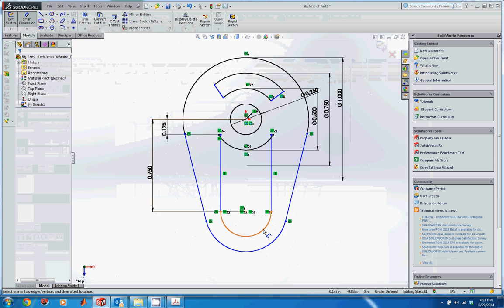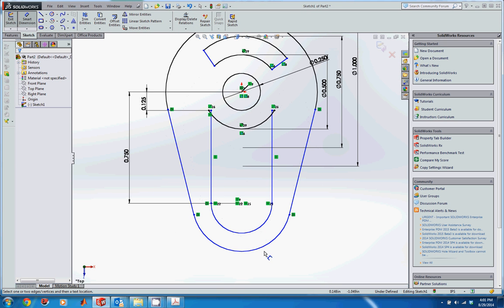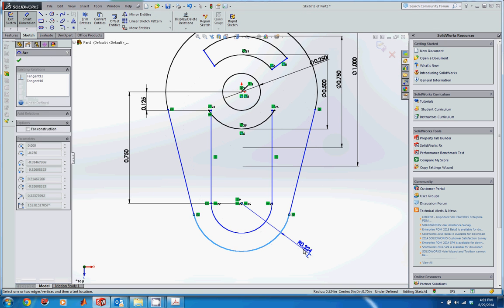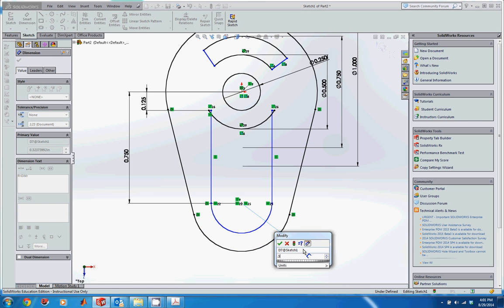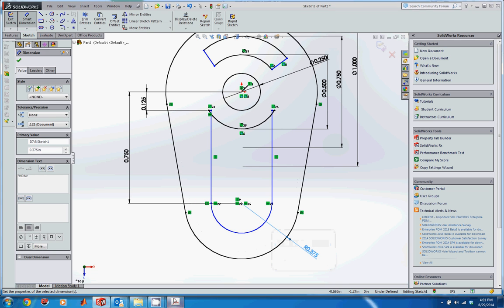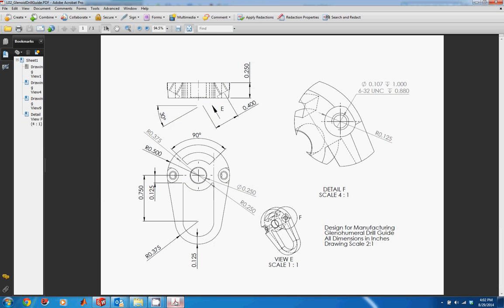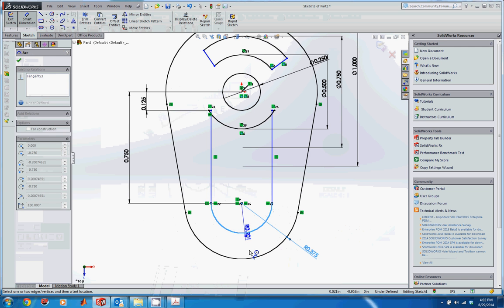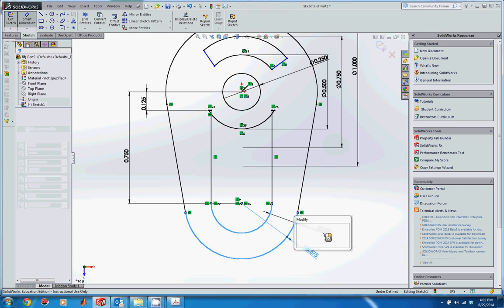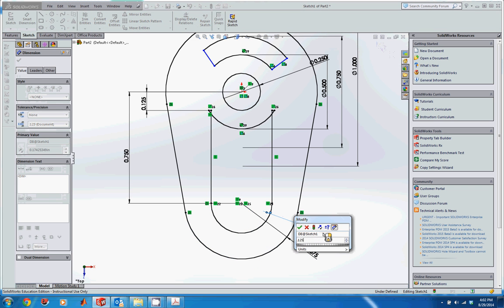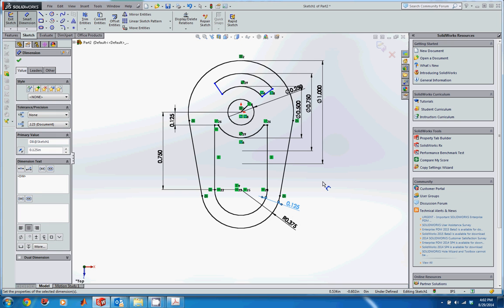And then we didn't put our dimensions in down here, so let's go ahead and do that. This outer circle should have a radius of 0.375. Again, we can check that in our drawing real quick. 0.375, right? And the thickness is that 1.25. So let's click on both of our circles, and then we'll place the dimension. We'll get 1.25. And then that should look pretty good.